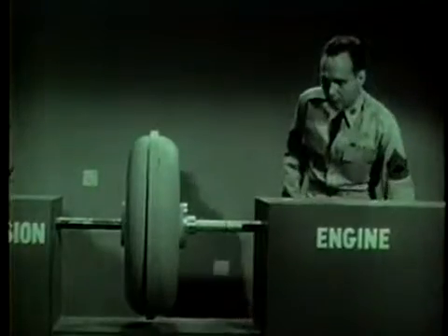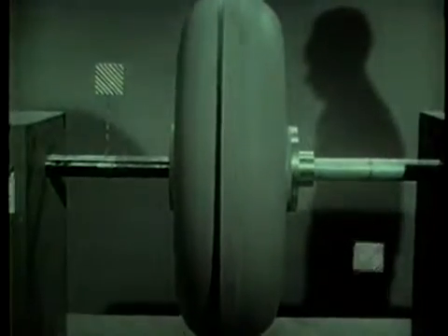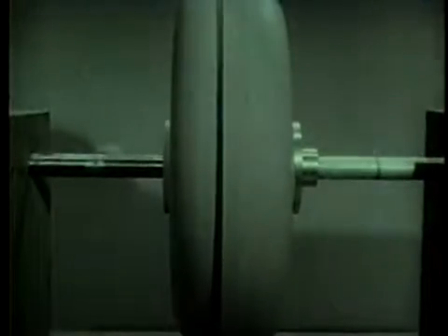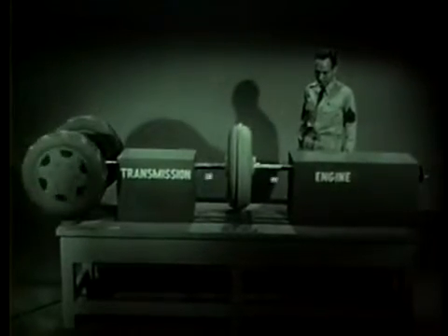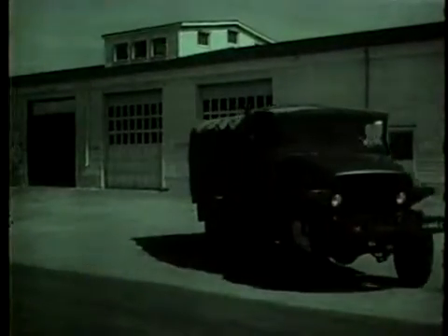At first, with the engine idling, it turns the pump so slowly there is not enough energy transmitted to overcome the inertia of the vehicle. As engine speed increases, the pump turns fast enough to transmit the required energy through the liquid to the turbine and on to the drive wheels. The vehicle now moves. Soon the turbine tends to catch up with the pump as the vehicle rolls along at higher speeds.